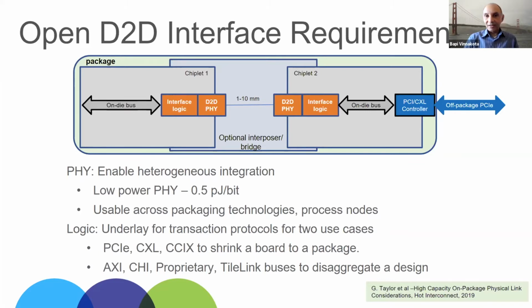So you say, I want a terabit per second between chiplets, and you say, well, your choices are, you can go for highly parallel buses, which means you're going to go interposer, and your product cost is going to be this, or you can go for a serial PHY. So this is one area which is not well defined, but we're trying to pay more attention to it within our group. We have something called an open mic where anybody with thoughts on it can come up and spend 5 minutes on the idea. This is one topic in which we're really interested: how do you represent downstream components early on in a way that makes sense to a product architect?